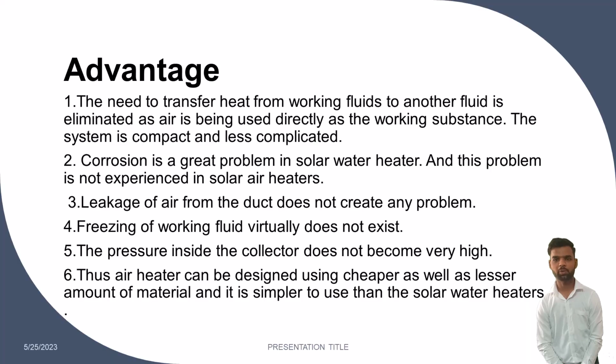The system is compact and less complicated. There is no problem of corrosion in solar air heater. No problem of leakage of air from the duct of solar air heater. Freezing of working fluids virtually does not exist. The pressure inside the collector does not become very high. Solar air heater is comparatively cheaper in cost as well as uses less material.